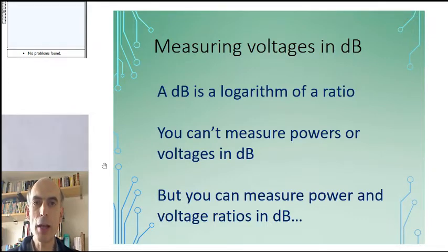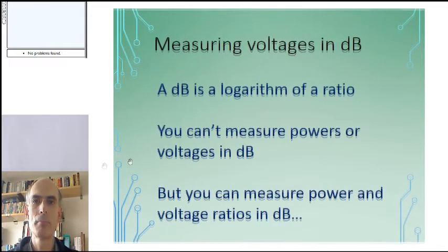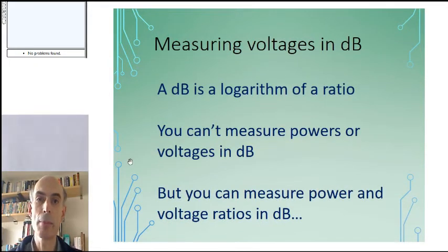In order to express a voltage in dB terms, we have to express it as a ratio to another voltage or another power. But we can do that quite easily just by choosing a reference voltage or a reference power and expressing our voltage or power as a ratio to our reference voltage or power.